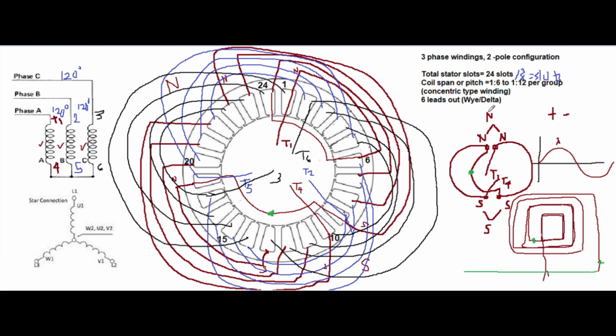So, what to take note here? The pattern, making two poles, north, south, north, south. They will cancel out as one north, will cancel as one south. So you have two-pole polarity. How to form the one group? That is one coil, another coil, another coil, another coil. This is one group or one pole, and one pole is equivalent to one group, and they are located 180 degrees. What is the characteristics of the first phase?